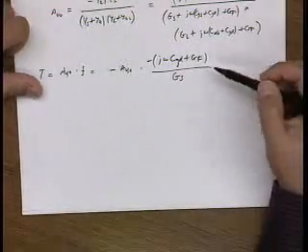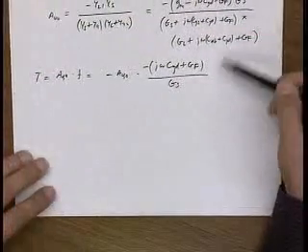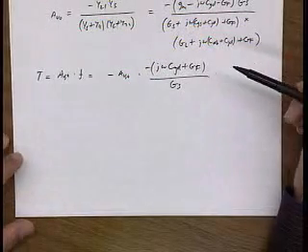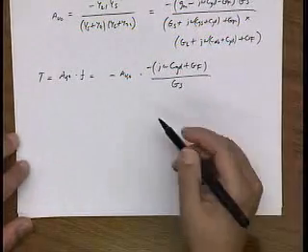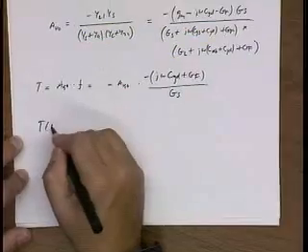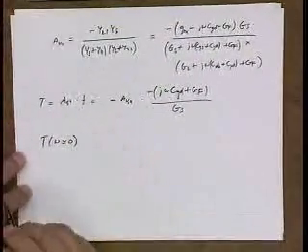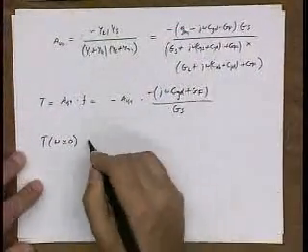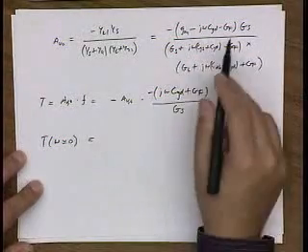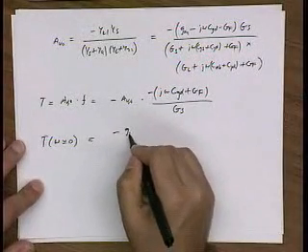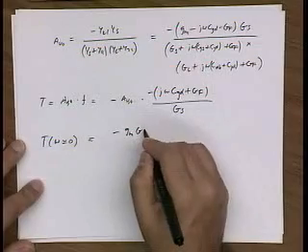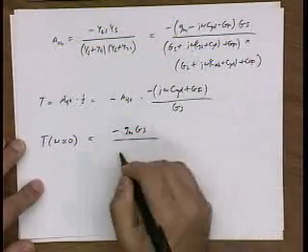Okay, and if I just multiply these two things, I have an expression for loop gain as a function of frequency. Well, let's calculate the low frequency loop gain just to see what we get. As omega goes to 0, all these j omega terms go away. So here I get minus GM times GS. Here I get GS plus GF.